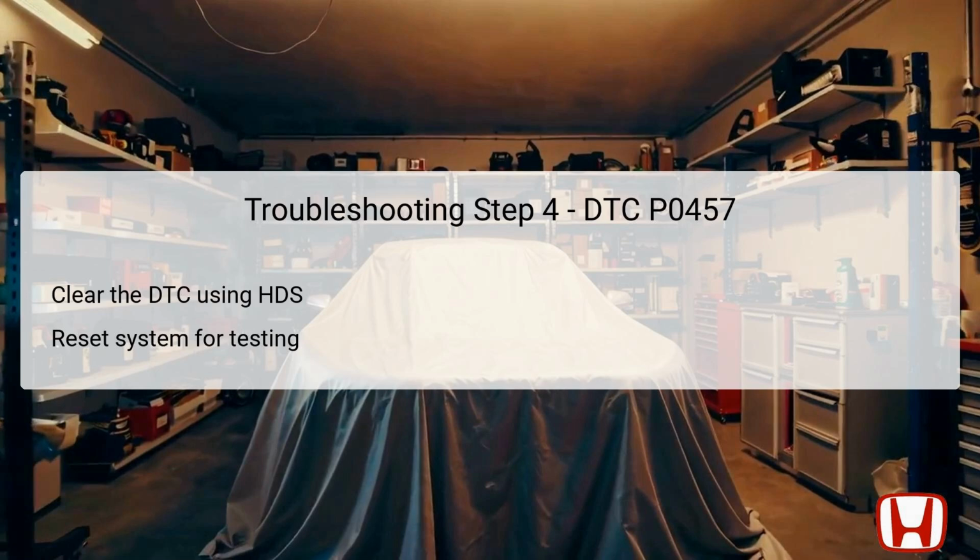During the fourth troubleshooting step, technicians will clear the DTC using the Honda Diagnostic System, HDS. The HDS is a sophisticated tool that allows for detailed diagnostics and troubleshooting within Honda vehicles. By clearing the DTC, the system resets any recorded faults, allowing for a fresh evaluation of the EVAP system's performance.